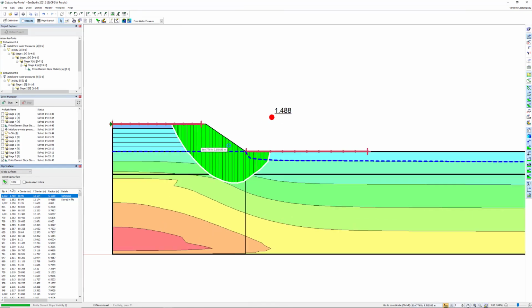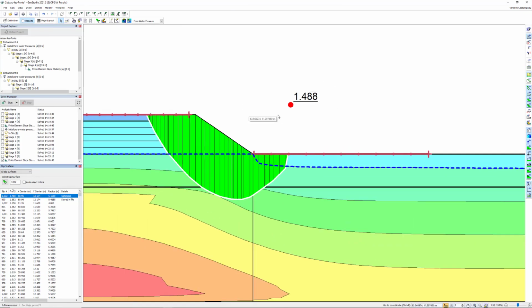The last analysis we will perform here is a dissipation analysis. In essence, a dissipation analysis is just a standard consolidation analysis, but in which no additional load is added. The goal is simply to let time pass as excess pore water pressure dissipates and the soil consolidates.